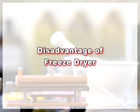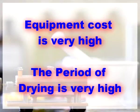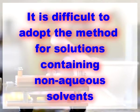The disadvantage of this process is that the product is prone to oxidation due to high porosity and large surface area. Therefore, the product should be packed in vacuum or using inert gas. Equipment and running costs are very high, the period of drying is very long, and the time cannot be shortened. It is difficult to adopt the method for solutions containing non-aqueous solvents.